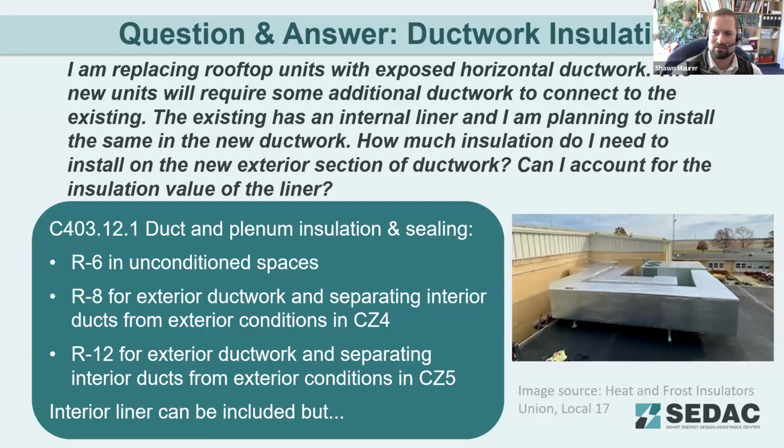So tying back to the original question of why might a fireplace not be allowed, the code doesn't allow space conditioning equipment outdoors. So if you're in an unconditioned space or an outside patio or something like that, you can't do an equipment sizing calculation for the system. Therefore, there's no way to properly size the system to comply with the code. So permanently installed heating fixtures outside the conditioned envelope for residential properties isn't allowed by the code.